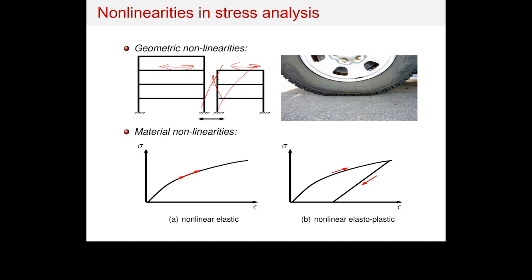This impact is not going to be a linear impact. This is going to be completely nonlinear behavior. And this type of nonlinearity is coming from the geometry. Buckling as well is a nonlinearity resulting from the geometry. And in fact, it's not going to be possible to get a perfect geometry. So these types of issues we have with the geometry would always result in some type of nonlinearity.